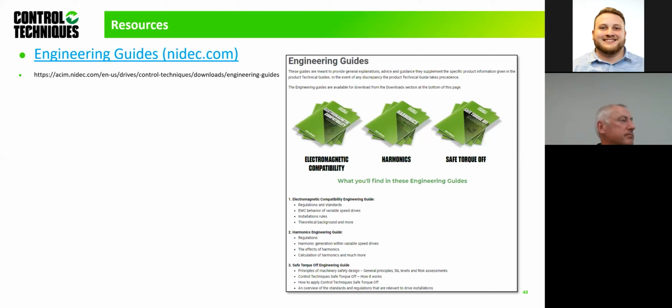Can harmonics cause actual physical failures in a generator, or is it only going to be performance failures? If it can cause physical failures, what parts of a generator are most likely to fail? And again, I'm not a generator expert. If you didn't derate the generator, it's more likely to be the rotor, because of the heat in the rotor, and I stand corrected on that. But if you didn't derate, say you had 50% THD and didn't derate, you'd start seeing things burn out and get hot.